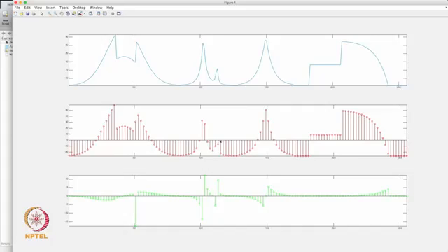Here we have performed only one level decomposition, but if I perform, let us say, 3 level decomposition, then I will be able to see those spikes coming in. So, DWT has a different signature here as compared to CWT for some singularities. Now, suppose I want to perform a 3 level decomposition, how do I do it?